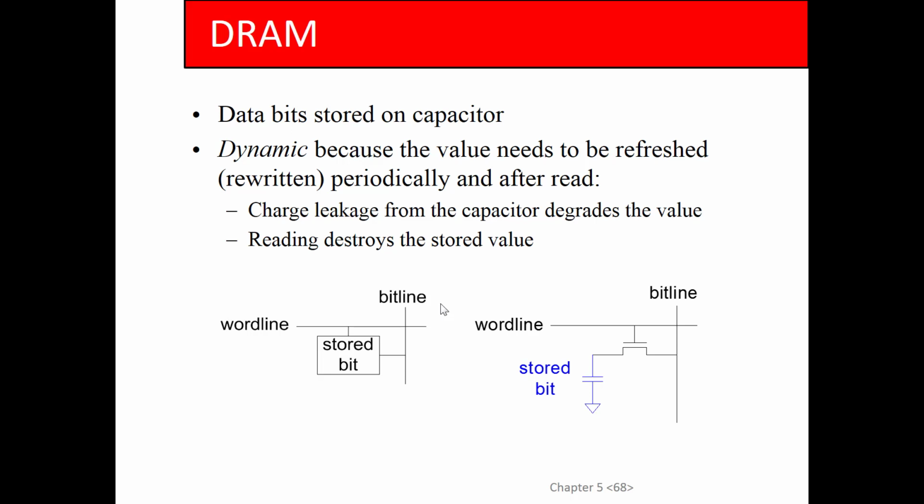One of the purposes of Moore's law is to shrink down those transistors to reduce the capacitance on the gates of the transistors. Also, Moore's law shrinks the wires down too. That reduces the capacitance on the wires. So we don't want capacitance, and CMOS chips are designed to not have capacitance. That is why DRAM cannot be made on CMOS chips. DRAM chips are made in a special process called a dynamic process that's designed to have as much capacitance as possible. So they're two different fabrication processes, and this is why you cannot combine logic and DRAM on one chip.